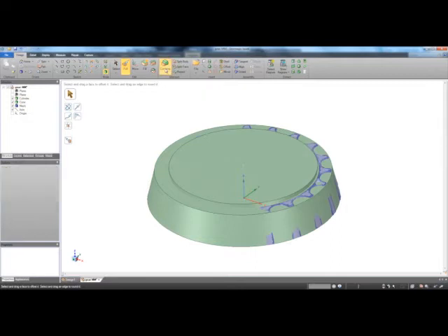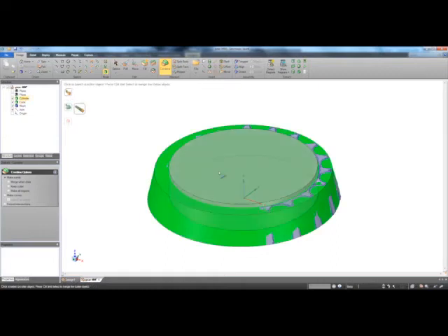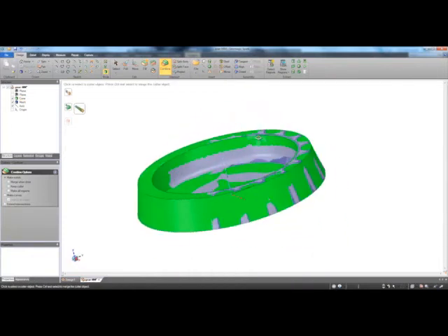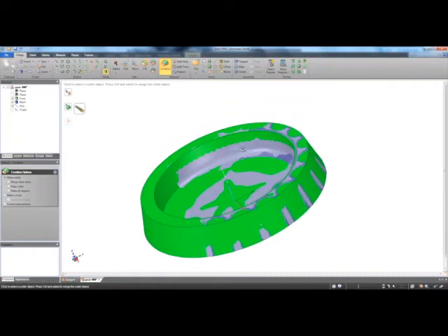So if I go to combine, I choose the body that I want to keep, and then I choose my cutter object. In this instance it is the cylinder, and then you'll see it turn red, indicating wherever I click with my left mouse button, it'll delete that body. So I'll left mouse button on there.